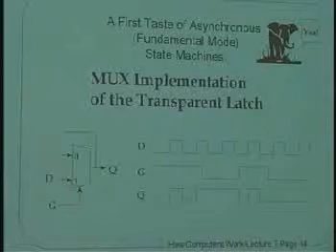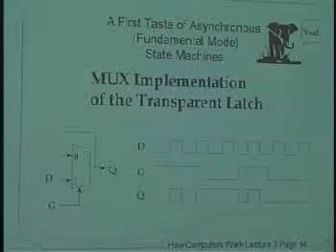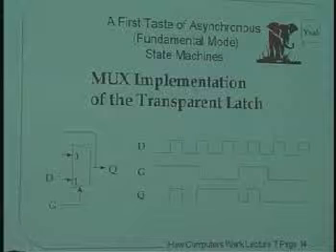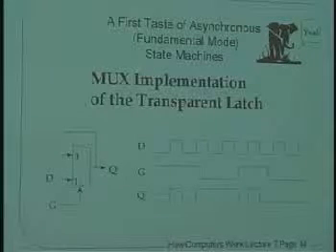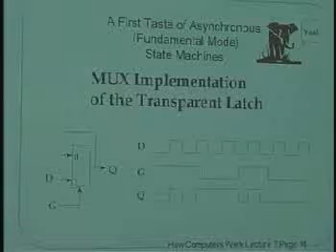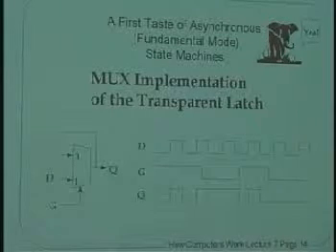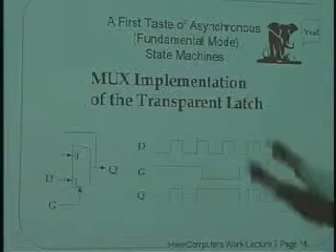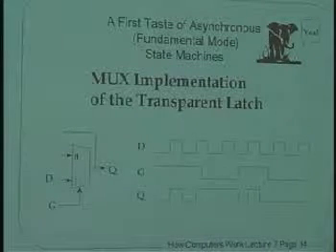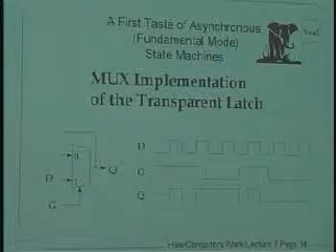Okay. So let's start to build some memory out of this thing. We have in our hands a hazard-free selector. Kind of a cool thing. G can go up and down. We've called it G now. And into the one input, I'm going to feed a data input called D. And out of the output of the selector, I'm going to take an output, and I'm going to call it Q. And here's how it works. We're building the memory here. When G is high, when the gate is high, the output Q is going to do what?